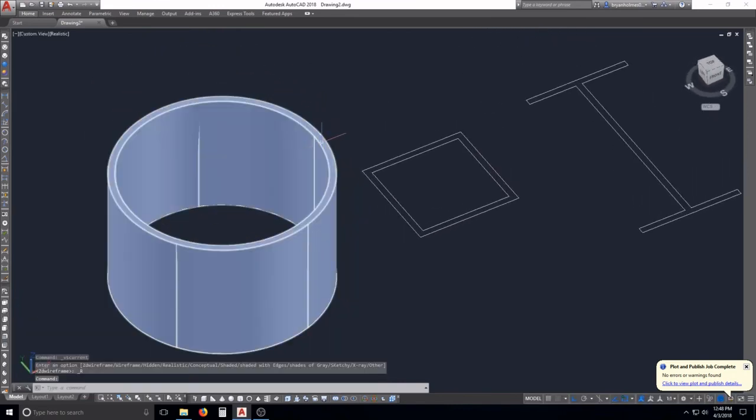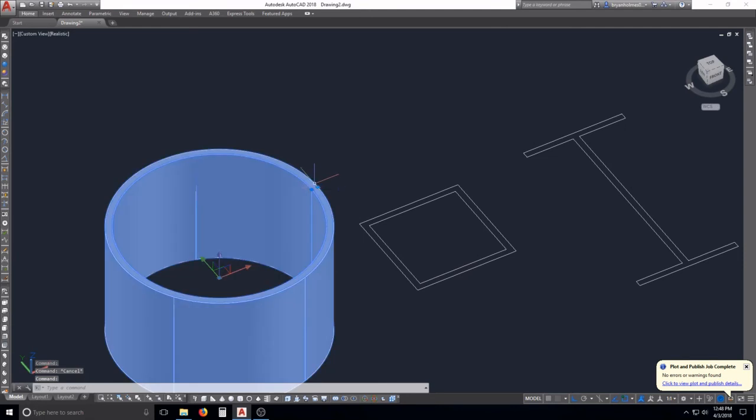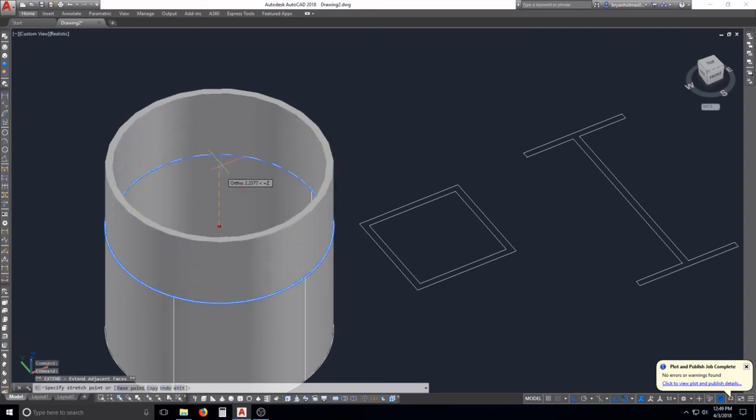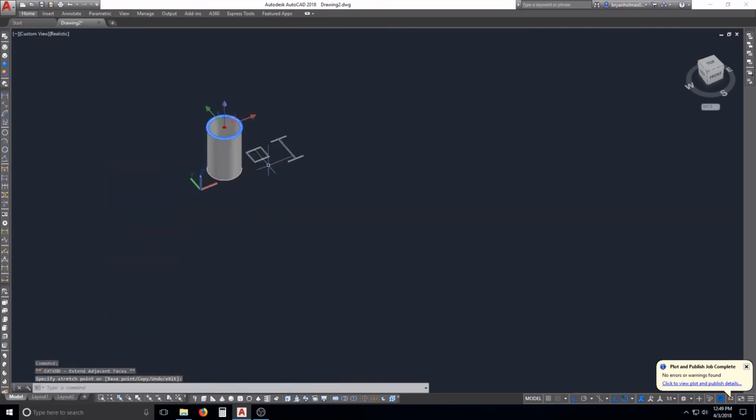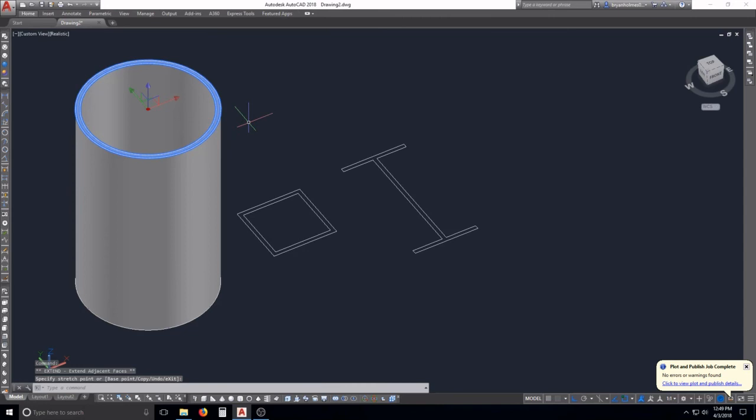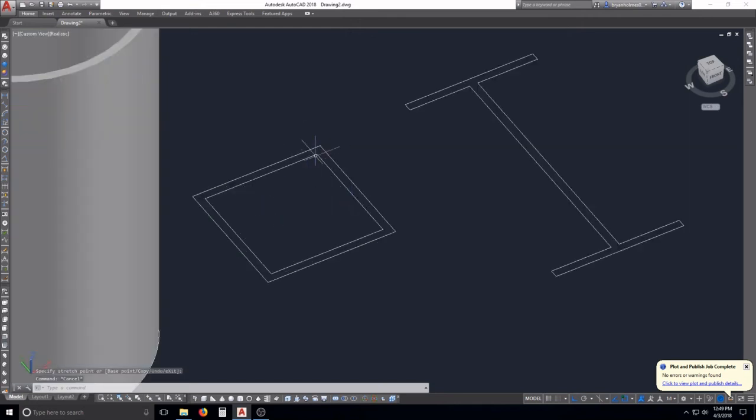And then if you want it longer, select it, and then Control, click, and there you go. You can make it taller. That way, I used to add sections and sections and sections and then join them all together. That was a pain before I realized you could actually just select the flat face and pull it up. Again, same process on this little guy right here.